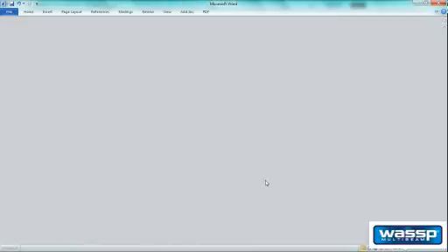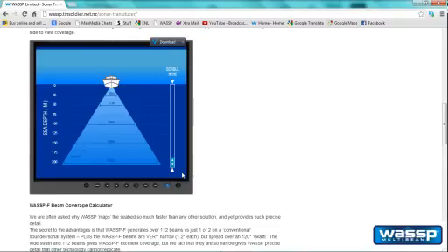So now we're going to have a look at a calculator that we've made. This calculator is available on our website, and here we can see in certain depths the coverage of the swath. So in 100 meters of water through a 120 degree angle, we can actually map below the boat and see 346 meters at the seabed level. That's our area of coverage, and obviously the deeper you go, the wider this coverage is. So in 150 meters water depth, we're profiling a corridor along the seabed, both acoustically and with our mapping, 520 meters wide.